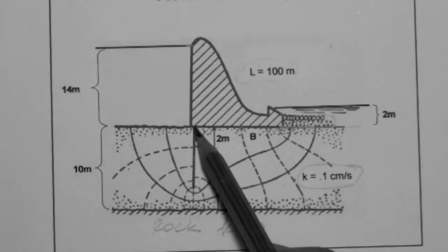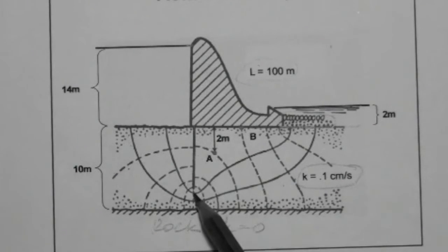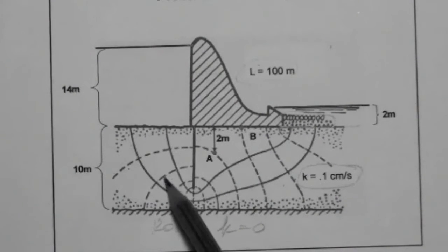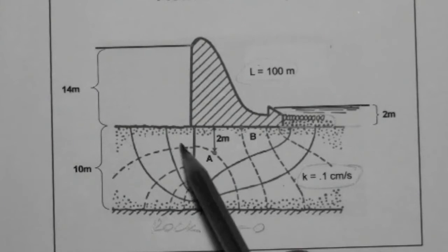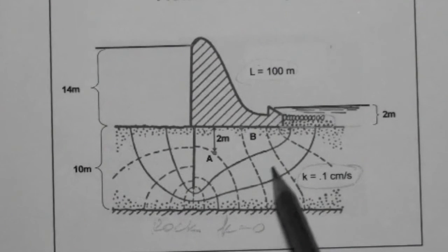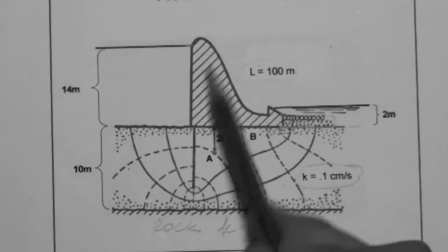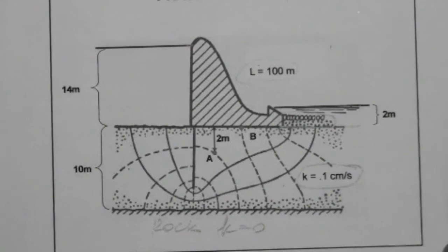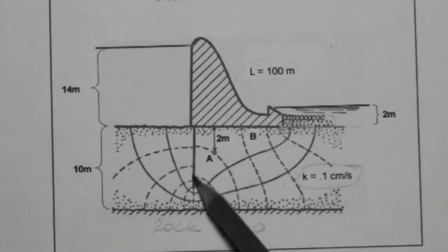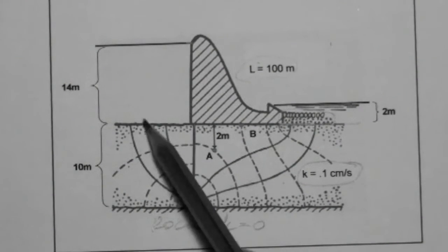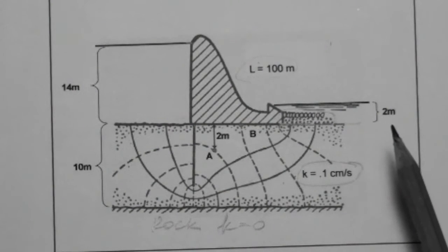And there's actually a wall below the dam that has been placed there to provide an obstacle for the water, so that the water doesn't have such an easy time going below the dam, but it has to go all the way down here to then come back up. Remember the idea of a dam is to retain the water. So if the dam can pose as an obstacle or have another system that serves as another obstacle for the water flow or the water seepage, then that makes the dam highly efficient.